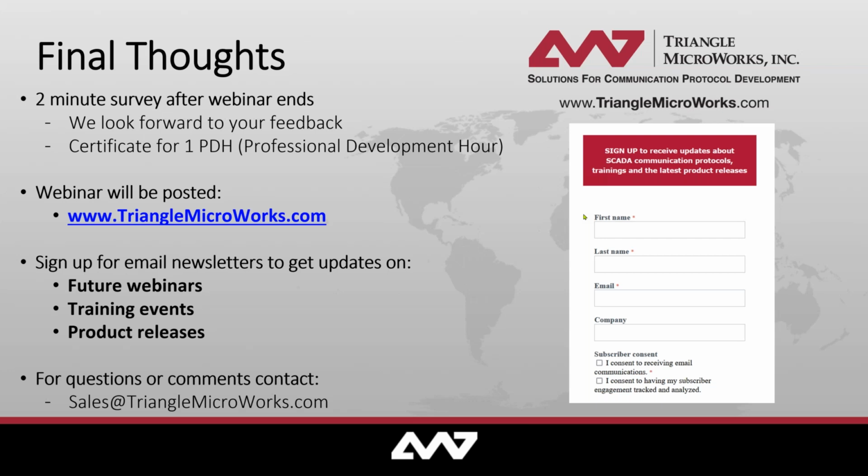Now, depending on the IED manufacturer and the system design, those XREFs might be contained within, let's say, the consuming logical node, the actual logical node that needs that message, or they could be contained somewhere else, like, for example, LLN0. We basically have an algorithm that tries to make those connections automatically, but it's a lot easier if they are placed in the specific logical node that will be using that message.